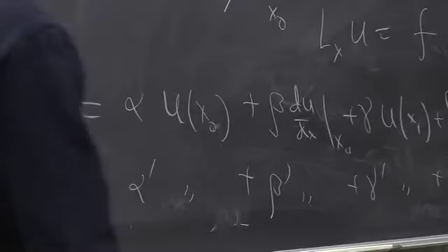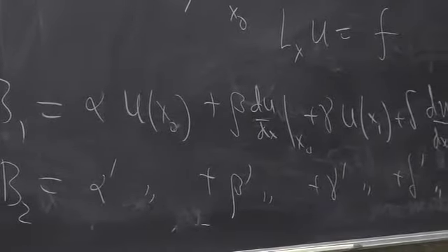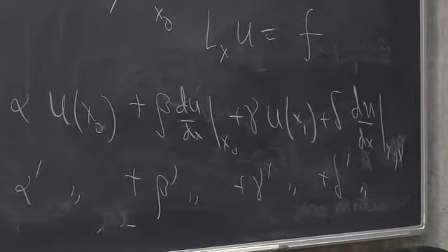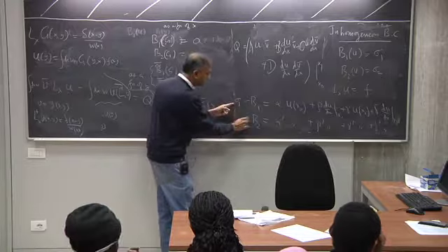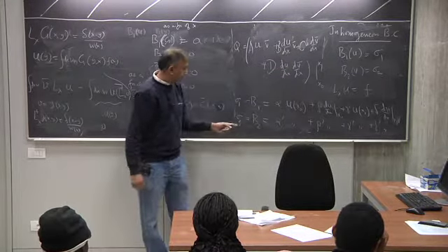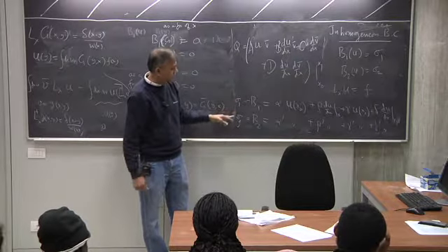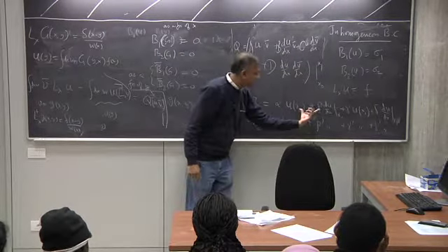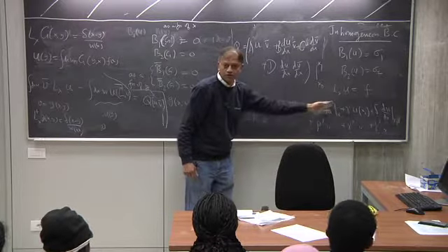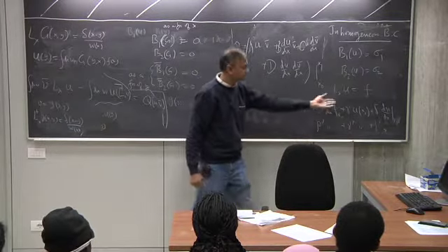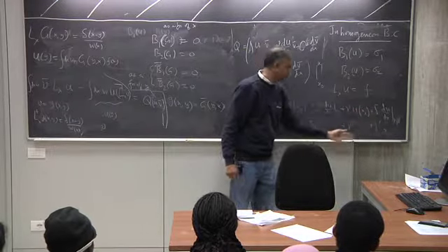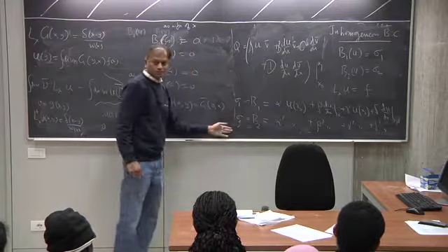Okay, these are the two boundary conditions. But using these two boundary conditions, what has happened now? This is equal to sigma 1, not 0, and this is equal to sigma 2, with these new boundary conditions. But no matter what, I can always eliminate two of these quantities. There are 2 equations and 4 unknowns, so I can write 2 of these quantities in terms of the remaining 2 quantities, and sigma 1 and sigma 2.